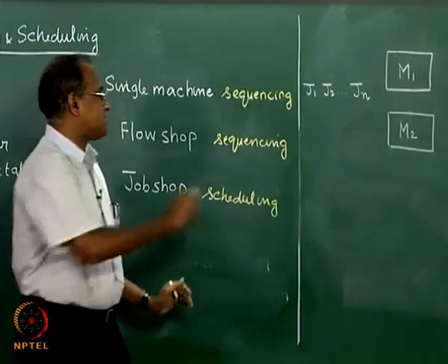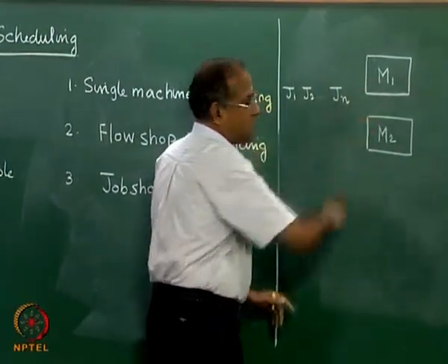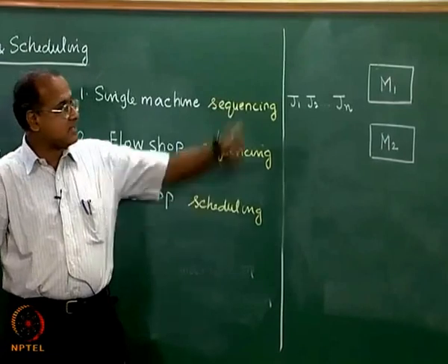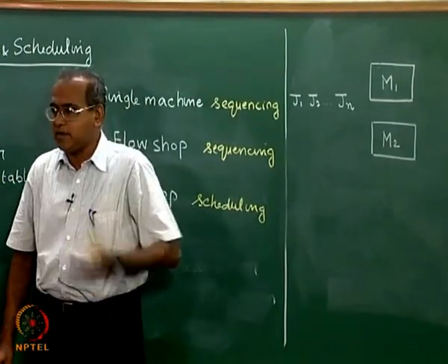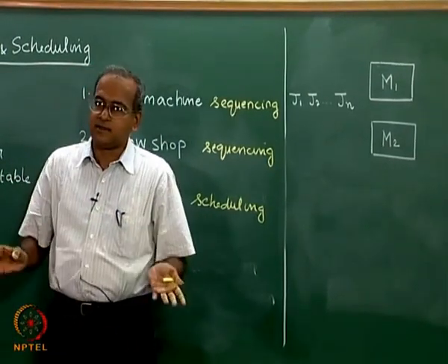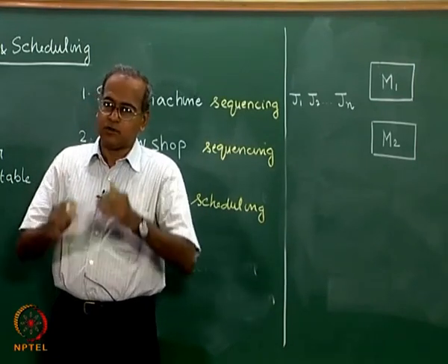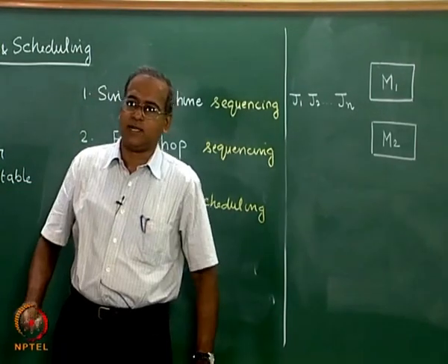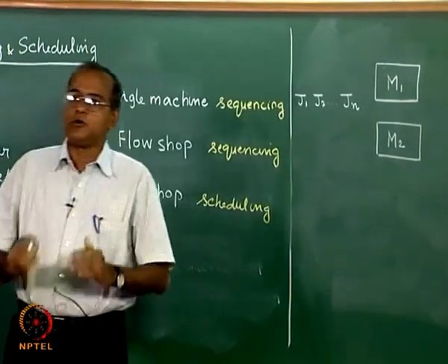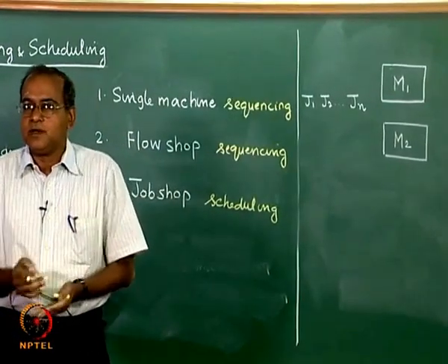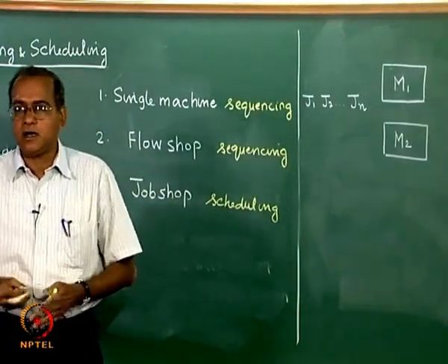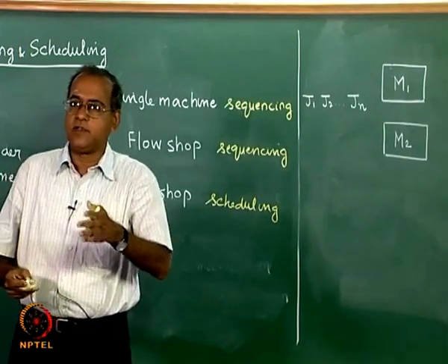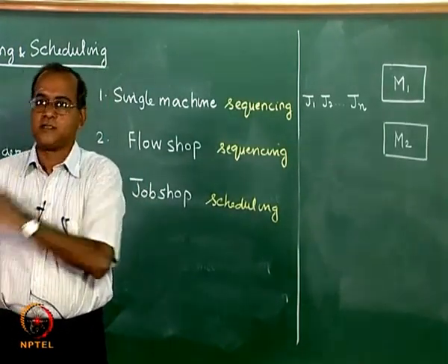If for example this takes 10 minutes, it can go to M1 or it can go to M2. It takes 10 minutes on M1, it takes only 8 minutes on M2 to do the entire thing. Even then we could send it to M1 even though it takes a little longer due to optimizing other objectives, but such situations are called parallel machine scheduling with non-identical processing.